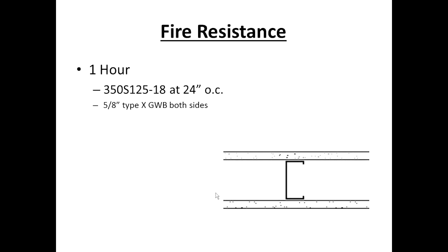There are 3 types of gypsum panels out there that come into play when we're talking about fire resistance. The first one is called regular core. You won't see any UL designs with a regular core panel. It has inherent fire resistance, but not enough where it can be used in fire resistive ratings.